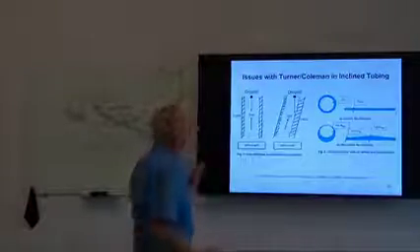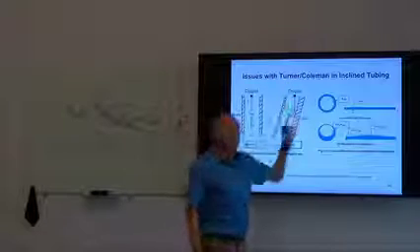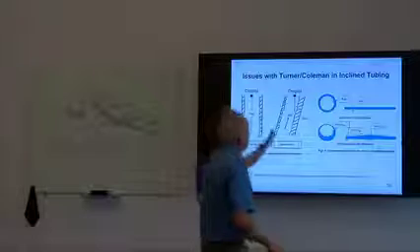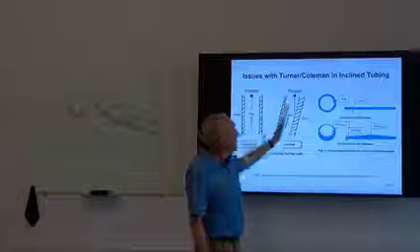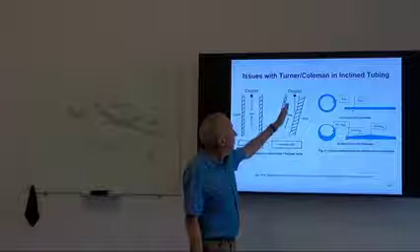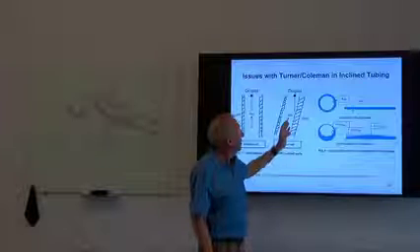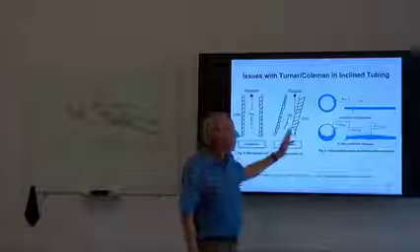So the condition when the well is inclined, our droplet still falls vertically. However, our gas direction, if we look at this vector of gas flow, the gas is going in line with the pipe, and the droplets, let's say, accumulate on the low side of the tubing wall.